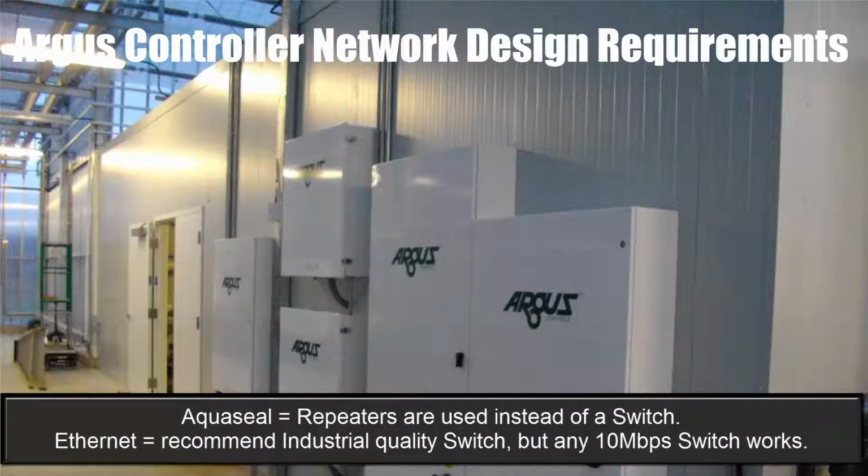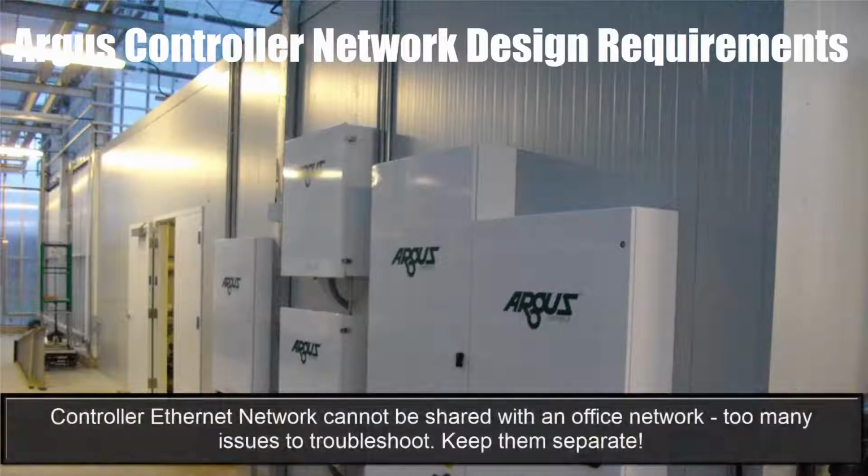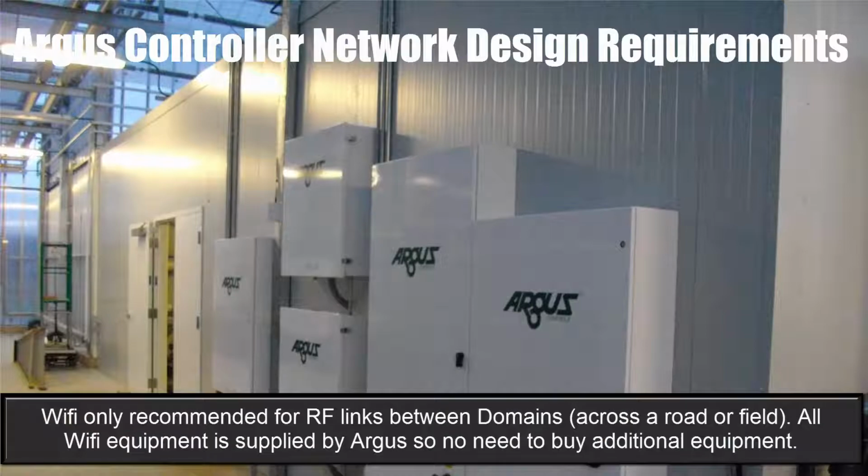For Ethernet cable, we recommend that an industrial quality switch is used, but any switch supporting 10 megabits per second should work. The controller Ethernet network should never be shared with an office network, as there are too many possible issues to troubleshoot. These networks need to stay separate. Wi-Fi is only recommended for RF links between domains, as we talked about, across a road or a field. This equipment is supplied by Argos, so there's no need to buy additional Wi-Fi components.